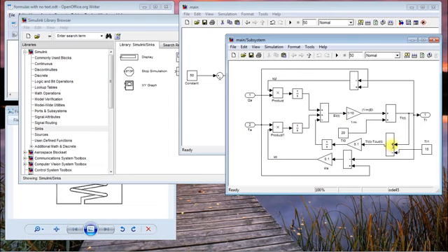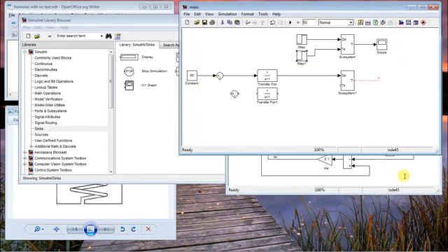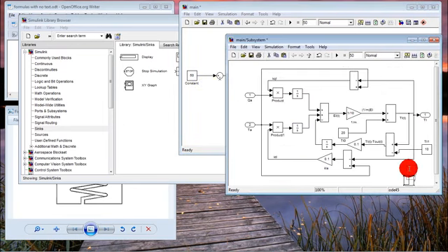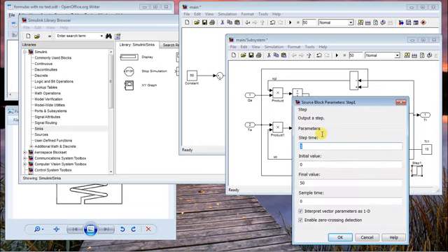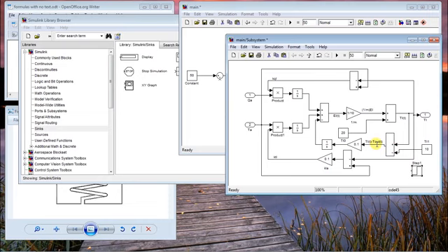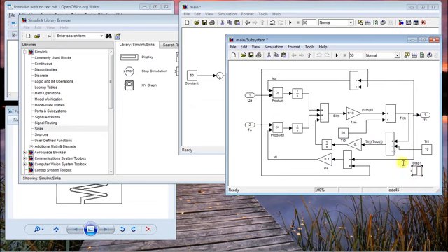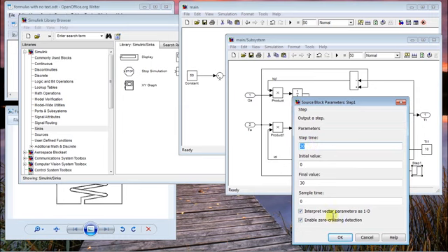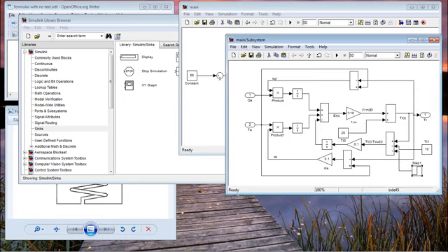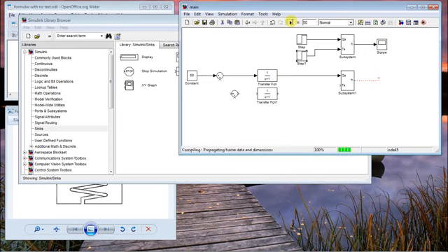And to simulate that, I'm going to place a step inside the model over here, which at the step time of 30 seconds will have an extra 30 degrees, and since the outside temperature here has a minus sign, we will have to place it with a minus sign over here. So what I am now actually doing is, at 30 seconds I'm increasing the outside temperature by 30 degrees, and let's see how the system reacts.